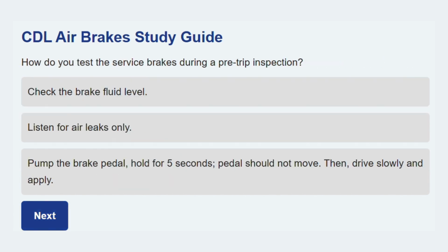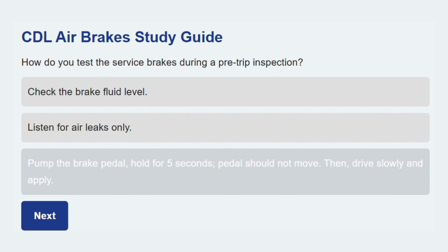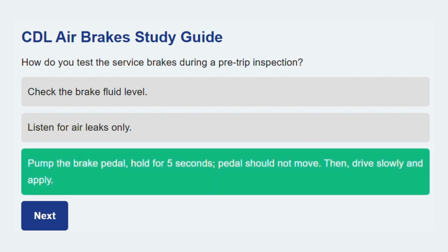What's after this? How do you test the service brakes during a pre-trip inspection? Pump the brake pedal, hold for 5 seconds, pedal should not move. Then drive slowly and apply. This comprehensive test checks for leaks, pedal stability, and proper braking function.